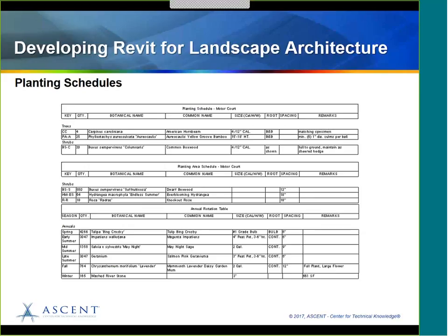And of course, if you're working in a true BIM or LIM, landscape information environment, we need to have the information gathered into useful reports, such as planting schedules. But no useful schedules come with Revit. So we had to customize the elements themselves and then customize the schedules. And when you get the course files, you can see how they're actually made. I'll show you a little bit about what we did today of how we created those schedules.